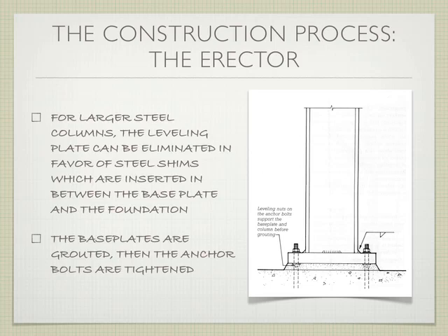We have a small 1-foot square piece and a column that's, say, 40 feet tall. If it's off just a fraction of an inch at the base, by the time we get up 40 feet, it's off 6 inches or a foot. It's leaning in one direction or the other. So you have to be very careful with how you get this perfectly plumb. And there's more to the strategy of these: stay a little bit loose until you get the rest of the building up, and then you work the whole building as a whole instead of just the individual column.